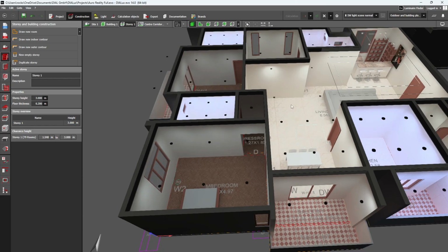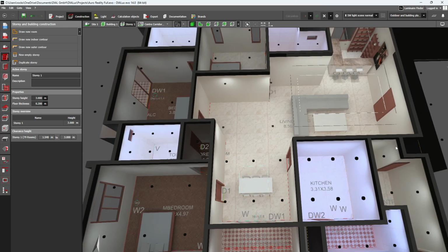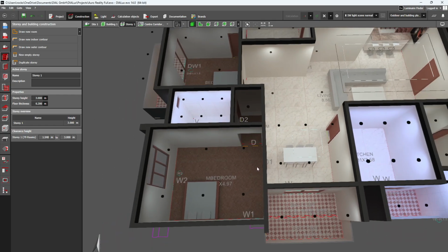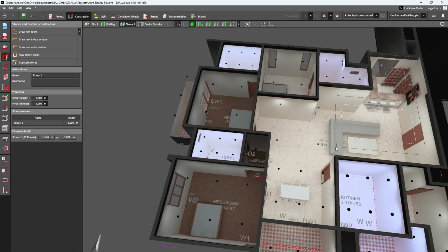Once we received the diagram in AutoCAD, we developed this room. We placed the windows, everything, and we put textures. We rendered the lighting. We checked the lux levels, and for every room there is a different intensity. Not all rooms are the same, as you know. The lighting lux for the kitchen is completely different from that of a bedroom. In fact, the CCT is different. This is 4000 Kelvin, this is 3000 Kelvin. As per those guidelines we have done this design.